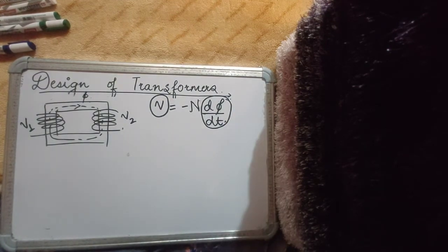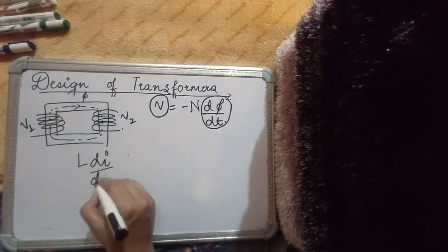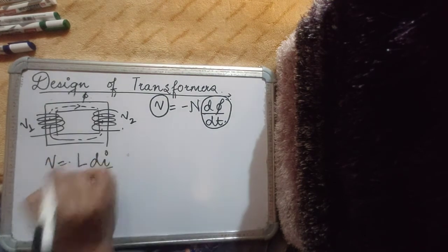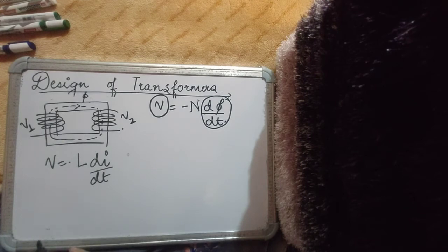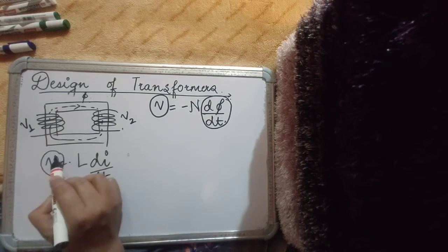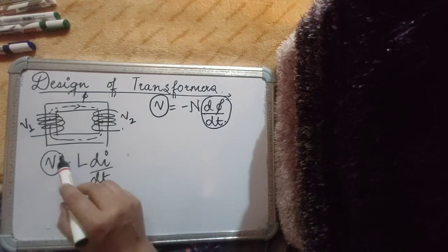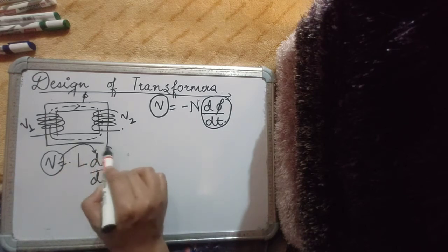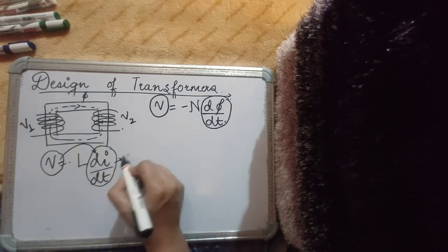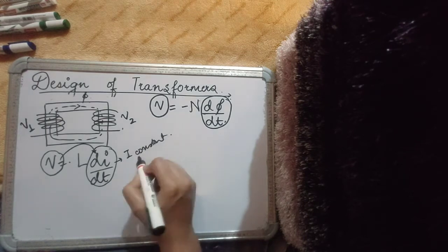Now let's see the analogous situation with inductors, which is simply V = L di/dt. If I see an inductor, basically an inductor will always induce some voltage across it such that the voltage is induced in such a way that it opposes any change in current and tries to maintain a constant current through the inductor, right?